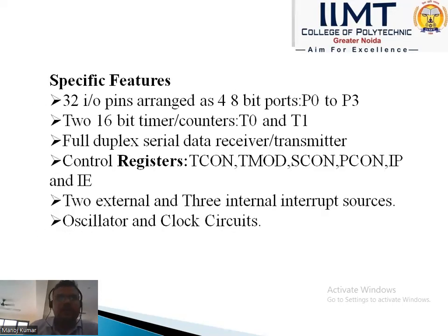Specific features: there are 32 input-output pins arranged as 4 8-bit ports P0 to P3, 2 16-bit timer counters T0 and T1, full duplex serial data receiver transmitter, control registers TCON, TMOD, SCON, PCON, IP, IE, 2 external and 3 internal interrupt sources, oscillator, and clock circuits.